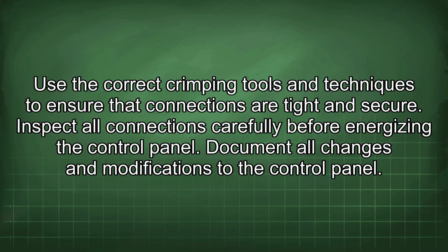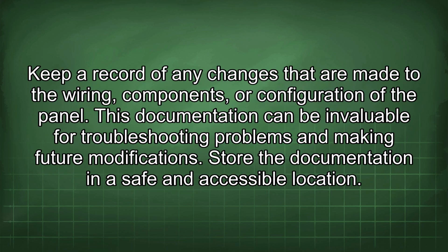Document all changes and modifications to the control panel. Keep a record of any changes that are made to the wiring, components, or configuration of the panel. This documentation can be invaluable for troubleshooting problems and making future modifications. Store the documentation in a safe and accessible location.